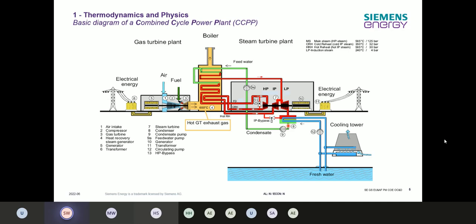Yeah, so we have water coming in, a condensate pump, getting the condensate over here to the feed water pumps. The feed water pumps increase the pressure for the whole water steam process part. So we increase the pressure one time, and from there it gets into the boiler with the feed water. This is just a basic diagram. Of course, on power plants, it can always be a little bit different.